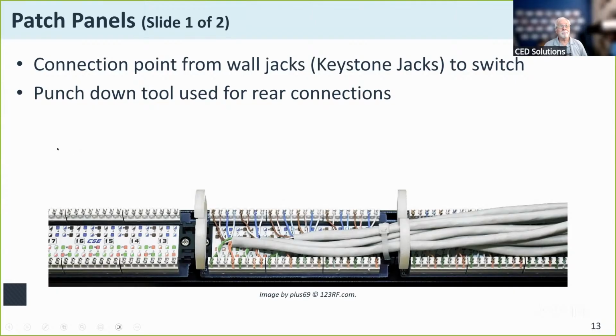I appreciate it. Now, this looks like the back panel as you would see going into a wiring closet. And there's a very specialized tool. We'll look at the tool later on. It's called a punch down tool that I use to strip back all of the wires and punch them right down into what they call these keystone jacks. The wires are color coded. They need to go in a very specific order in the jacks there. But this is set. These don't change.